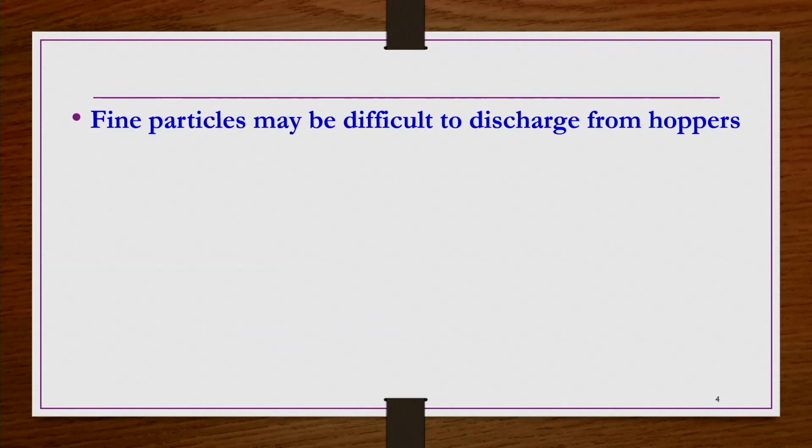Now, we have also seen that fine particles may be difficult to discharge from hoppers, because sometimes they cling to the wall surface of the container and form bridges, as I already drew and showed in a hopper, something like this. You may have fine particles filled in here entirely. Then the fine particles may stick to the walls, and you may not be able to discharge them properly, right, like this.